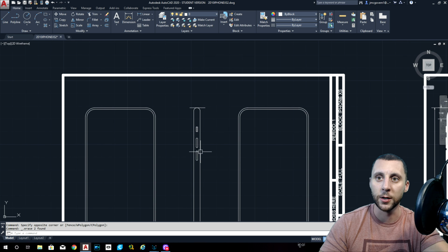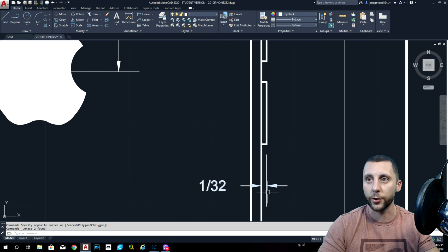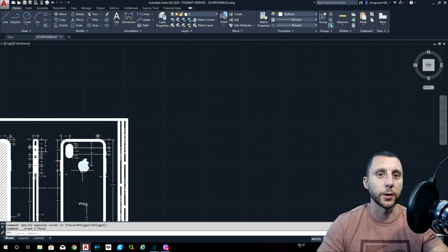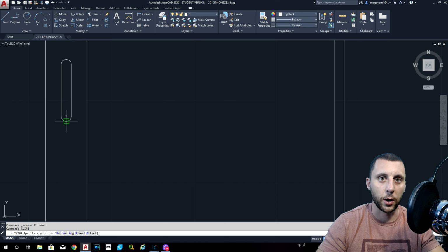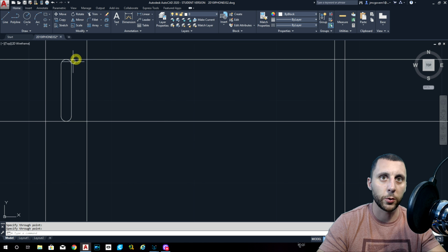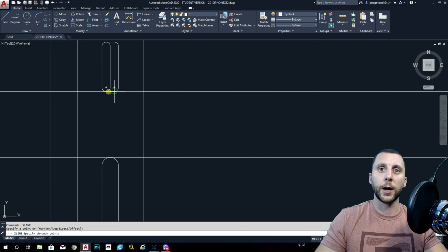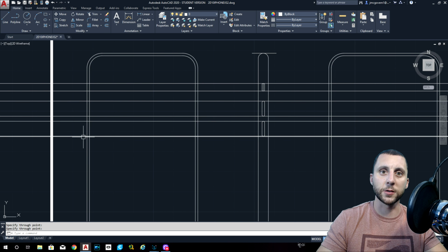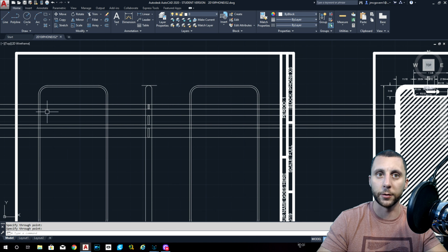Okay, we got the buttons. Now, the buttons stick off the side of the phone by 1/32. And even though this is curving around, it's still going to look like just a square button from the side profile. So we're going to do a construction line, X line, off of this point, same on this button, top and bottom of the sleep/wake button. That's going to tell us where these buttons sit on the left side of the front view and on the right side of the rear view, because you're just flipping the phone over, right?